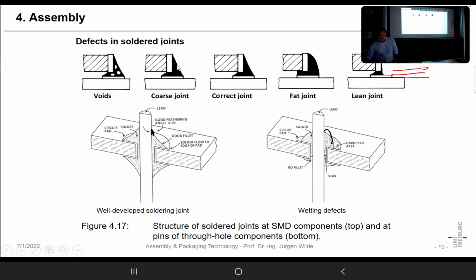And also in former times, that's also a good sign how clean your solder is. So in reflow soldering, you typically buy your paste and you know the cleanliness, because it's specified. When you do wave soldering, over time, impurities accumulate in that solder bath. That solder bath can be 500 kilograms of solder, but as time goes on, you always have leaching of some metals because you always dip something into that bath.